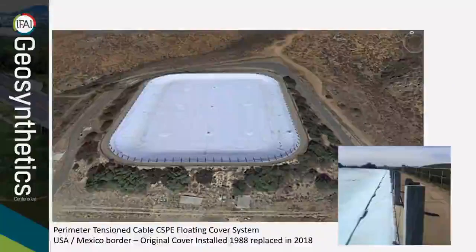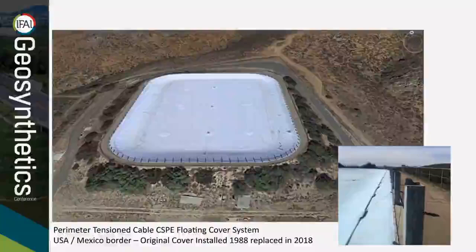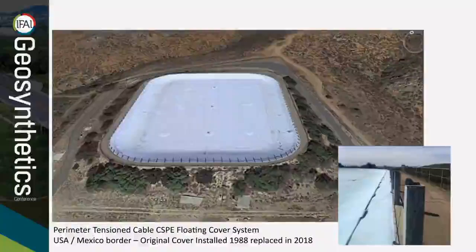And this slide shows a perimeter tension cable CSPE floating cover system that was installed on the USA-Mexico border. The original cover was installed in 1988 and replaced in 2018 after 30 years. And the picture on the right actually shows the tensioning towers and cables pulling a reinforced edge, keeping the cover nicely tensioned in application.